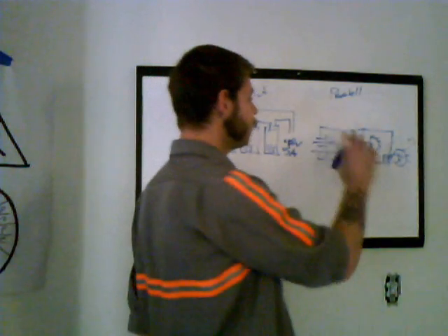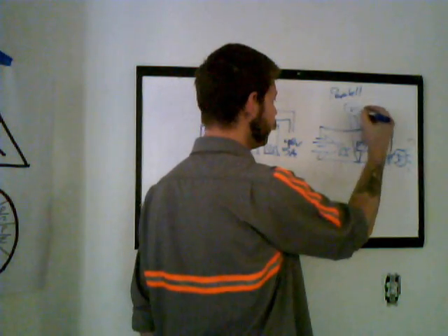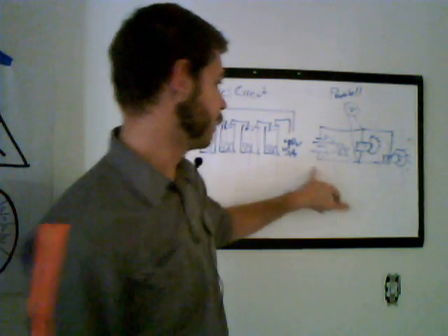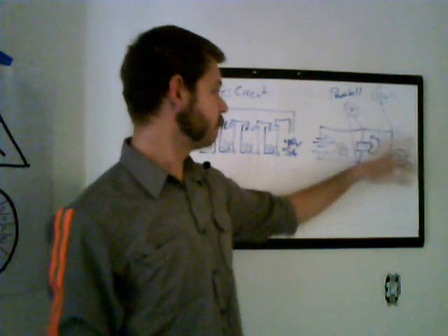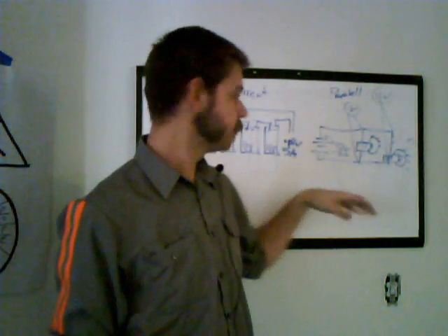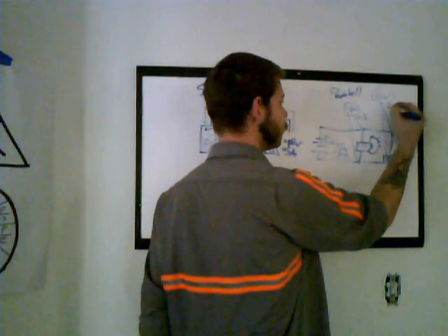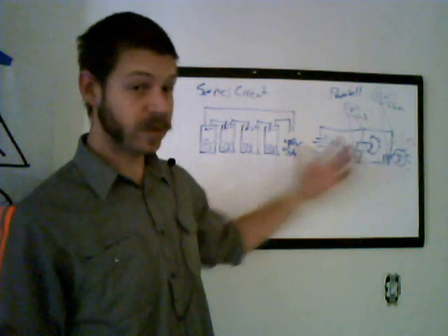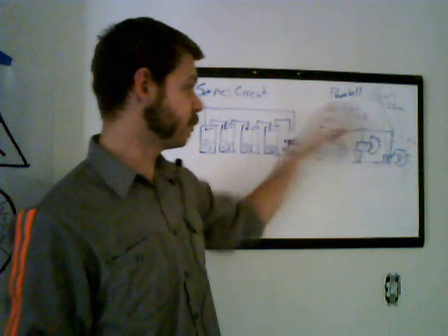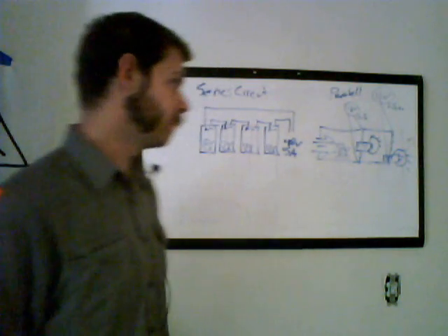Now, if you were to measure right here, you get 12 volts, because basically you're just measuring here. It's just a wire that connects these two. Same over here. So the voltage drop across this light and this light is all the same. It's 12 volts anywhere you measure it. However, 5 amps? No, I don't think so. This one's 2.5 amps. This one's also 2.5 amps. The rule is the amperages going into any given section have to equal the amperages going out of that section. All of these amperages have to add up to this amperage. It's just the way things roll.